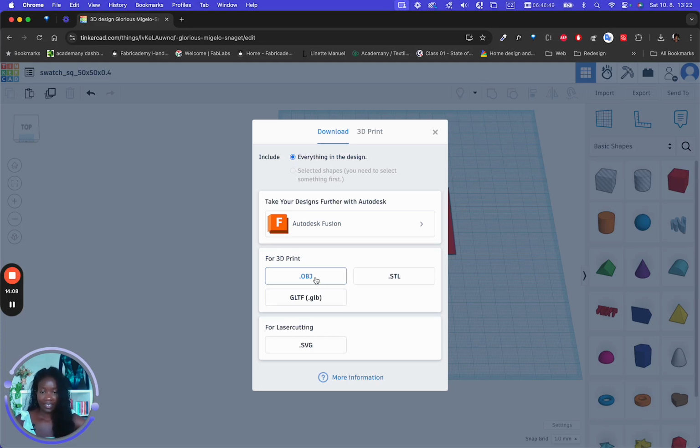But we don't need that for our printers because the final color is always defined by the color of the filament that we use in the printer. So we can export only simple STL, which is just a collection of all of the points of the object. So without the materials, without the structures, just the simple object.